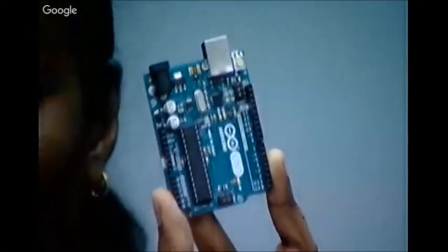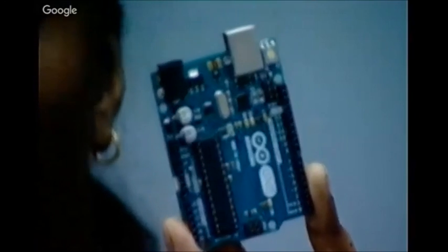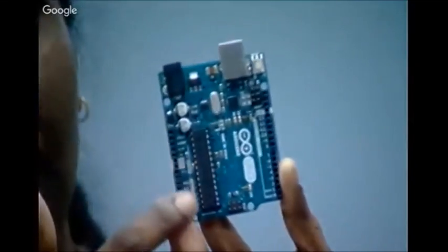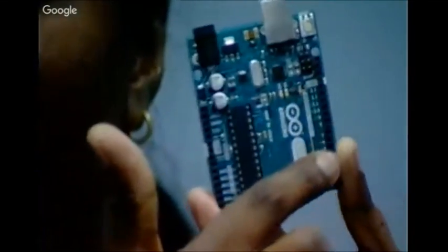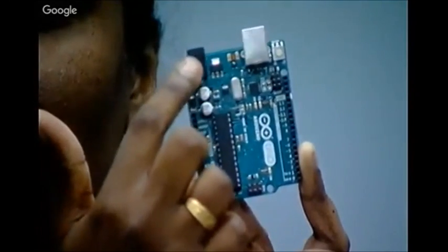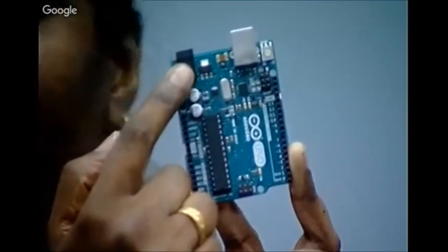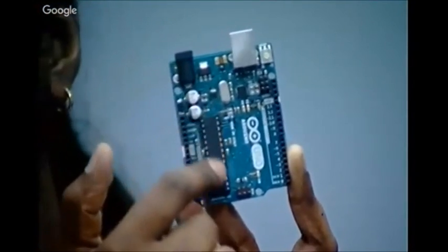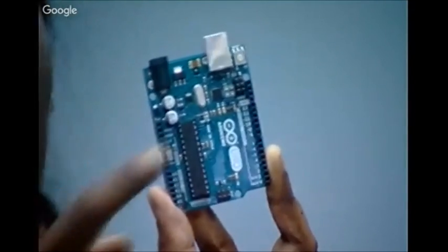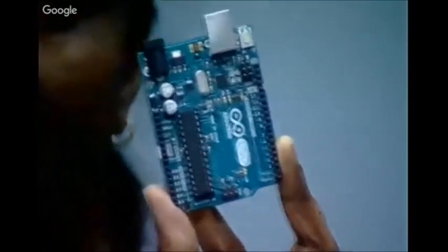Okay, I'll show the same thing on your screen, so that you will be seeing all the input output ports and the controller, everything. I'll be explaining it more clearly. So you can see all the pins. On this side you have the digital input output ports. Here I have the analog input output ports, A0 to A5. This is the USB port. This is your power supply port. If you want to operate it individually, you can give power supply using this. And this is your ATmega 328 microcontroller, that we will be seeing in your PPT now.